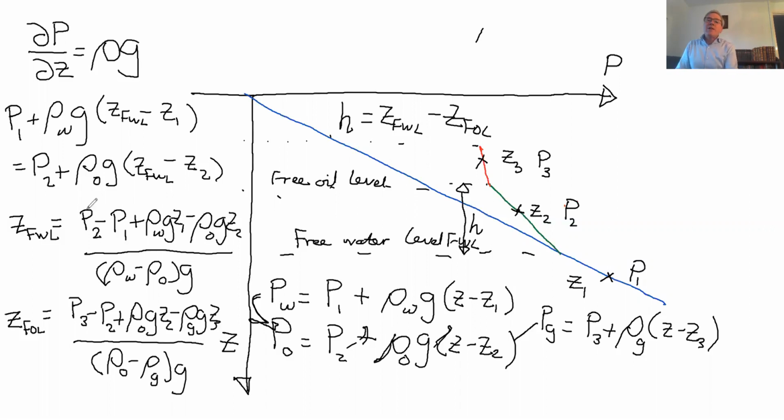The only thing to bear in mind is don't be silly about units. P is often quoted in megapascals. Well, you need to convert that to pascals. Don't get mega and other things confused. They try and make sure that everything is done in strict SI. Sometimes people get a bit confused with this. They think they're doing petroleum engineering and they know that we use funny units, so they think when we do SI units, we don't do them properly. And then you get yourself into a complete muddle. Okay, so this is the first calculation.